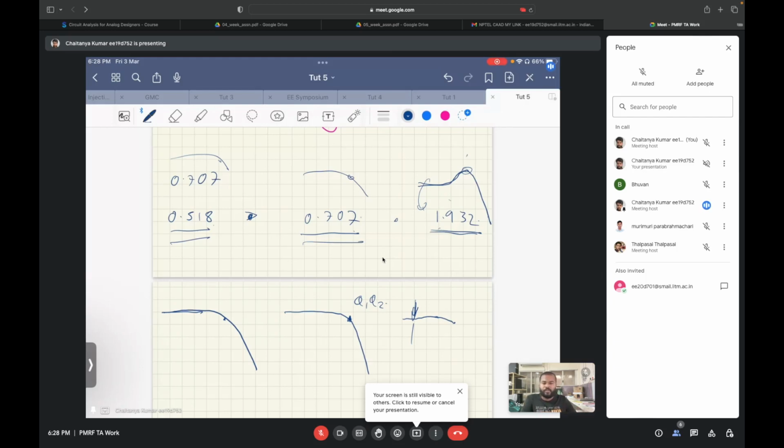So doing dynamic range scaling of individual biquads is actually suboptimal. The reason is that there you won't be getting the benefit of the attenuation that you are getting from the previous biquads in the cascade. Are you getting my point?